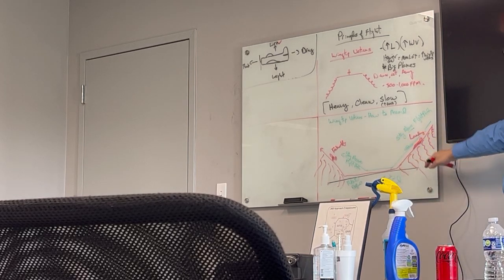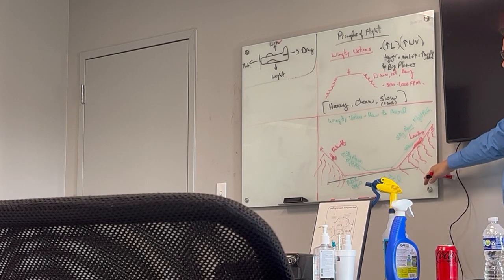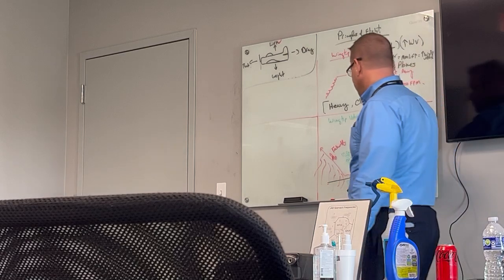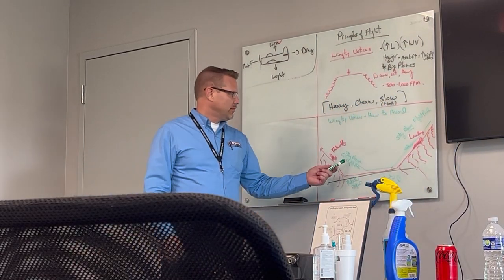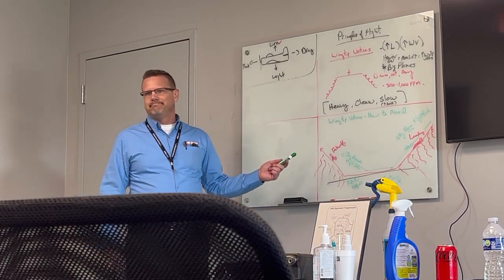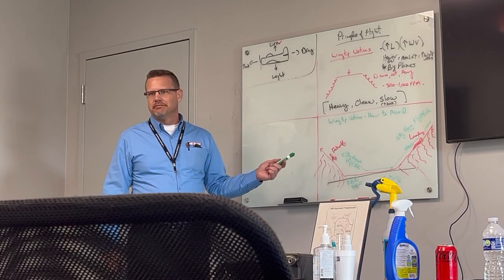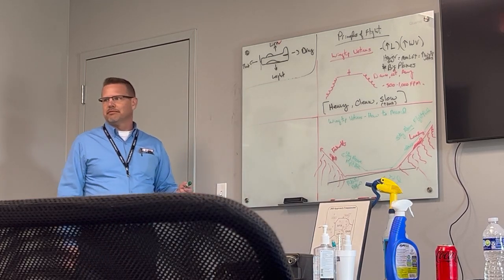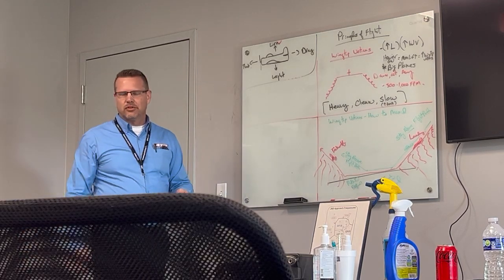So how do we avoid them? Stay above, fly the bowl, touchdown beyond, rotate before, climb above. And if you can't climb above, then after you rotate, you get to a safe altitude, sidestep to the upwind position. So if you've got a 30 degree wind coming off your right, do a sidestep, climb out to your right, because the wind's gonna blow the vortices the other way.